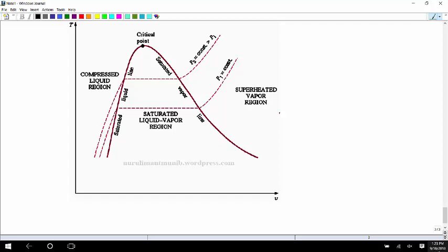And molecularly, what happens is the water molecules are being forced to spread way apart. And so any heat you add to the saturated liquid at that point is just going to spreading out, pair by pair, spreading out these water molecules. And so the temperature stays at 212 degrees, but the volume gets larger. Now if the water starts to boil in a pan, it's hard to keep track of all the water, but if it's covered and somehow you still are controlling the pressure, it will get a little harder now.